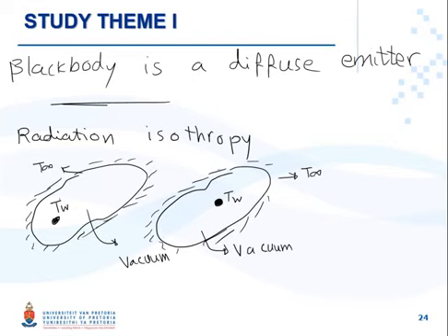So now we can say that regardless of the position of the black body inside the evacuated enclosure, it will reach the same equilibrium temperature. And when it reaches equilibrium, the emission will be equal to the absorption, because we just talked about it, and that will be the maximum corresponding to the temperature of T infinity. Why?